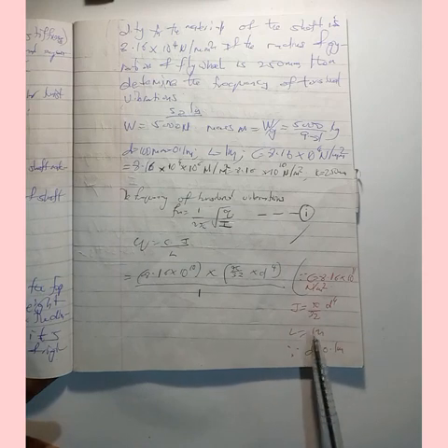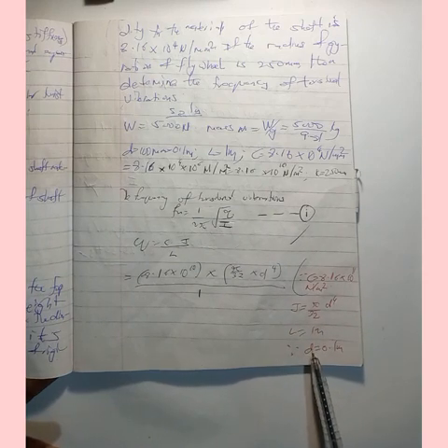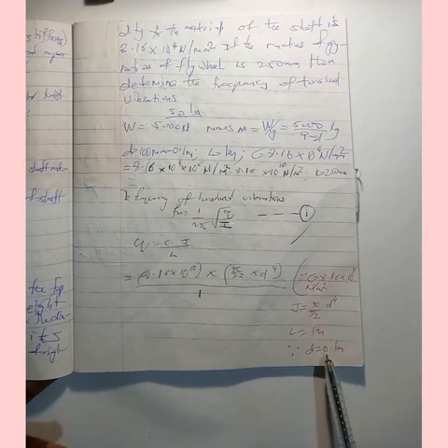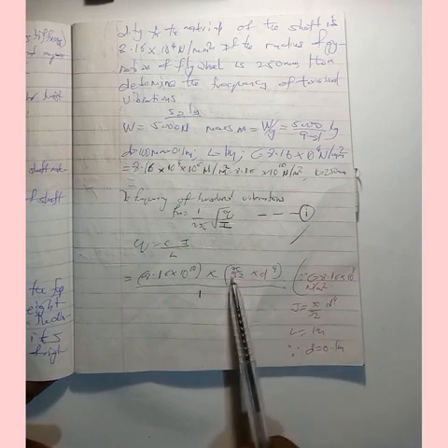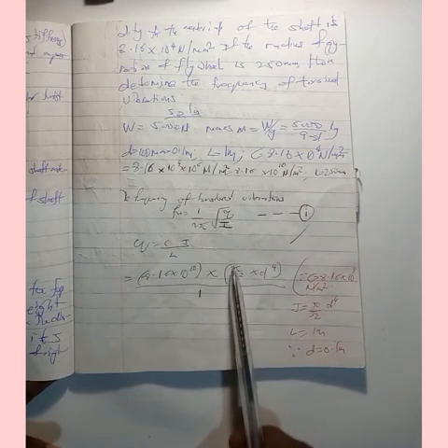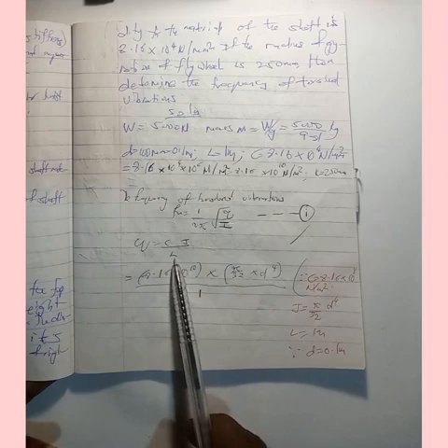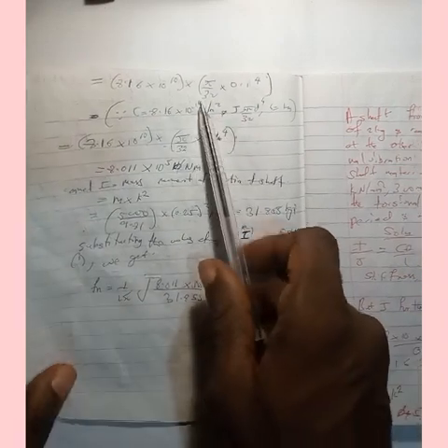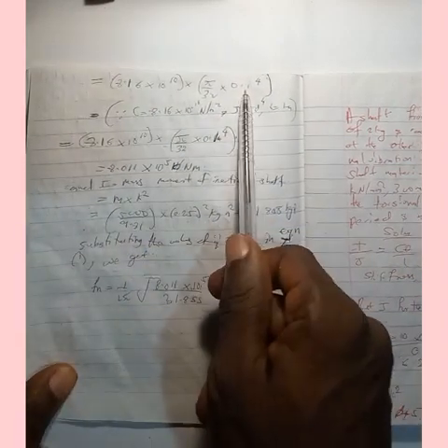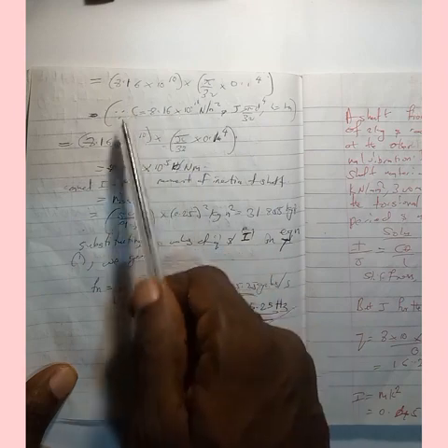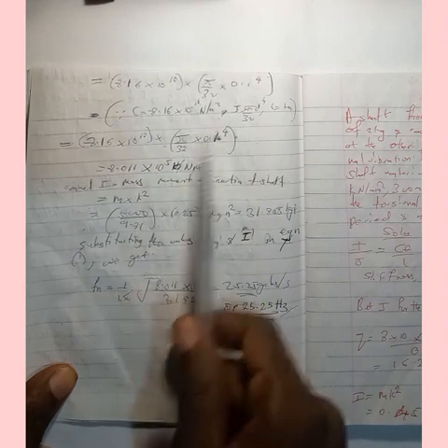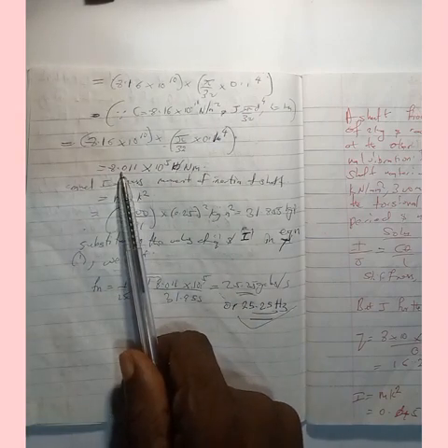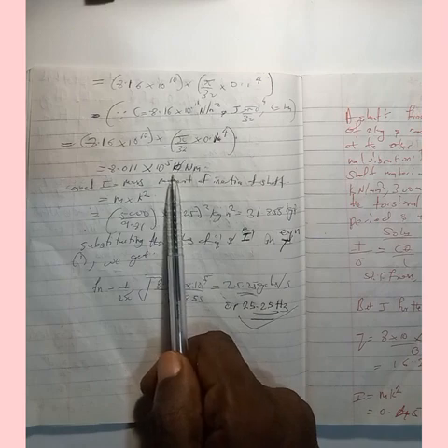Now there's a calculation here. We know that our d is 0.1, so by the time you apply 0.1 into d, we are going to have a value for the polar moment of inertia here. What is L? From the question, L is 1 meter. So eventually we have 0.1 raised to power 4, everything over 1. By the time you simplify this further, we eventually have our q to be 8.011 multiplied by 10 raised to power 5 Newton meter.